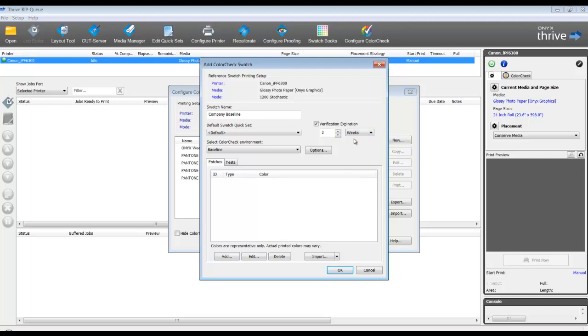When determining this amount of time, we want to find the right time where things start to drift or change in our process control or in our environment settings. By starting out 1 week to 2 weeks to 3 weeks, we slowly, gradually migrate up until we find what is our timeline. It is important to note that this should be a consistent time, meaning it's not 1 week and then 3 weeks and then 2 days. If we've got a very volatile environment, our process control schedules will be very hard to track.